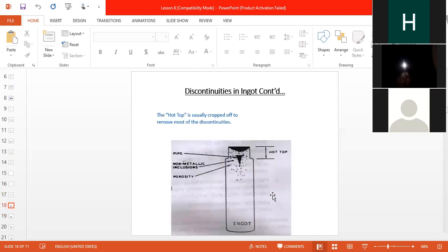Now after that, suppose here is a cavity, and if you want to do rolling, then what happens? Suppose here is a cavity, and after that you do rolling. In rolling, the ingot is pressed, maybe into rectangular or square. So that defect also changes. After rolling, this size is reduced, so this defect size is also reduced. Here the diameter is more, but here it is smaller. This thickness is reduced. This flat defect is known as lamination. So these are laminations, and this lamination comes in rolling.